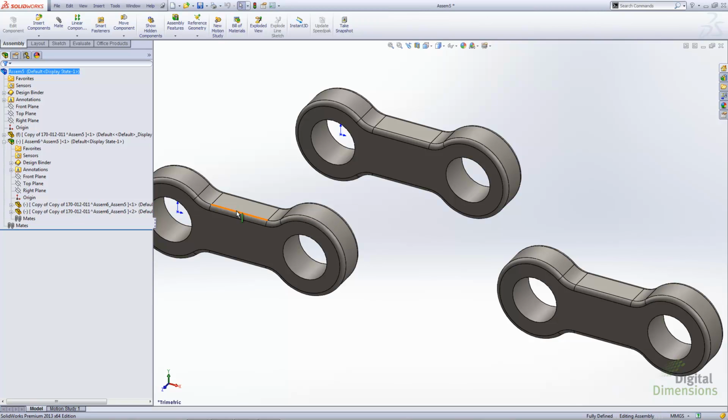The reason for this is that the new copy has no link to the original. Just by definition of virtual components, these are components that live and are embedded within the parent assembly file. Since we've made that change, we can actually do a move in the traditional sense. It's going to be a copy.